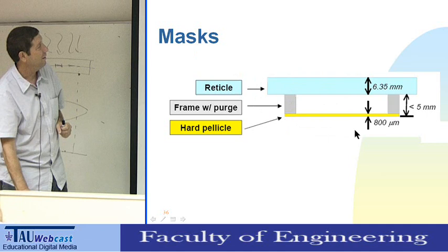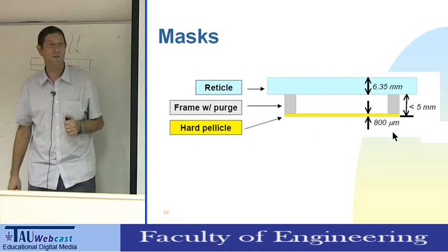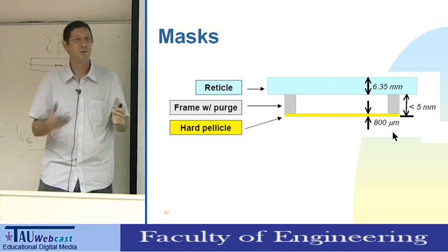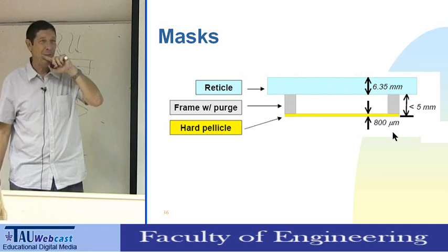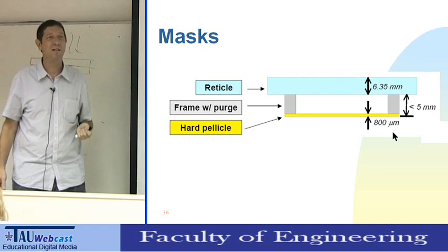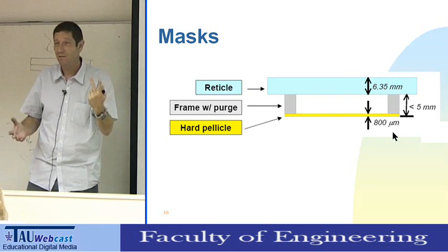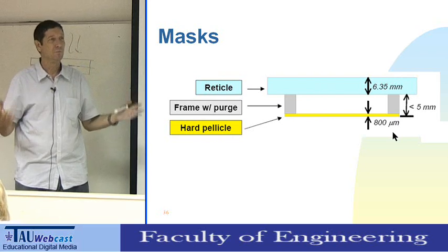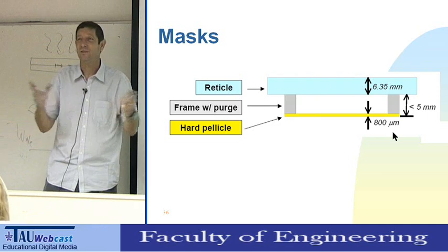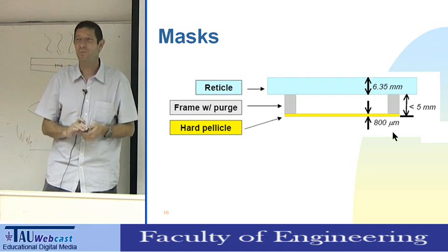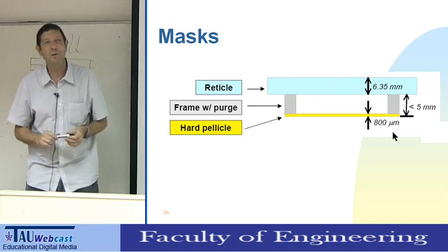And if we can end the lecture with the economics of lithography, the cost of masks is also going up exponentially with time. So not only do they become more complicated, with pellicles and more features, if we do double patterning, we need twice the masks. So the masks become a good part of the process, and they're not cheap. A good set of masks can cost a few hundred thousand dollars. So see you next week, and we'll talk about EUV.